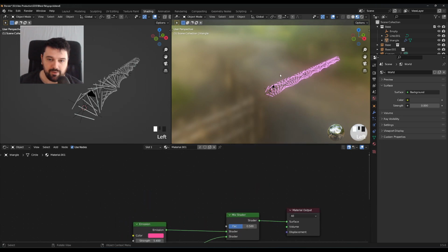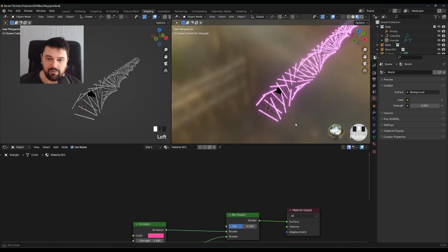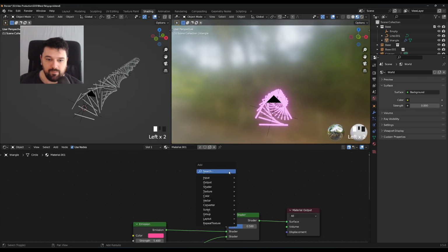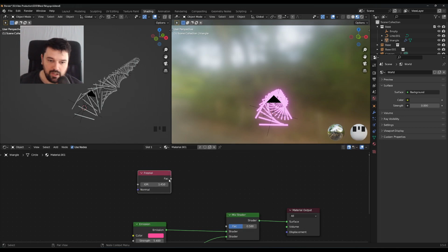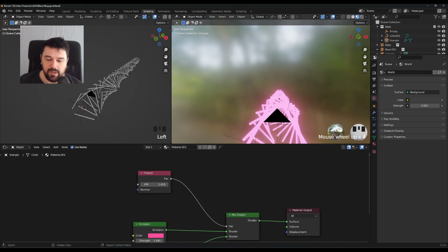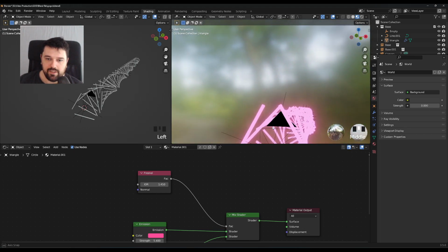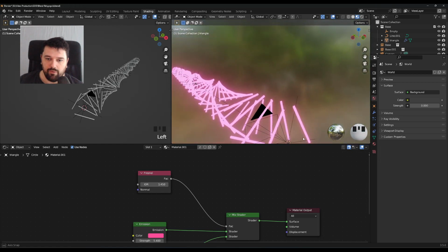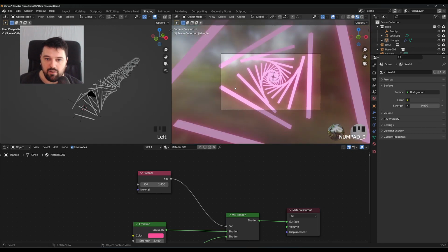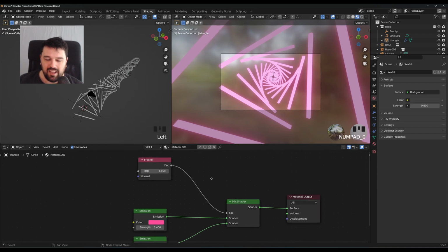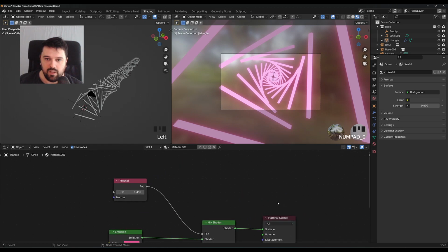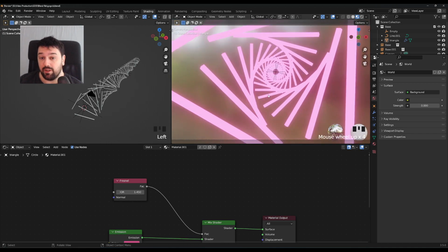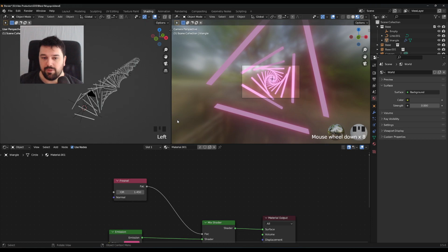At the moment they're mixed with a factor of 50-50, so we're getting a literal true mix of the 2 colours. But what we want to do is use a very special node called the Fresnel node to make it so that the mix between them is based on the angle of your camera when you look at the object. So you'll see the edges are slightly darker than the inner. And that's kind of the effect you get when you use your neon. And that's kind of the effect that you're looking for when you're creating a neon style object.